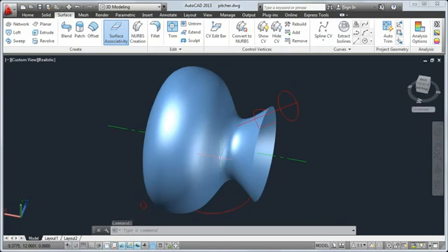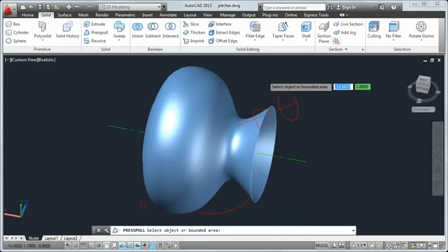So far, so good. Now I'll extrude this circle into the body of the picture. This solid will be used to trim the surface and form the cutout for the pour spout. From the Solid tab, I'll select Press Pull. Notice the circle highlight as I hover. AutoCAD has detected the circle as a closed object.